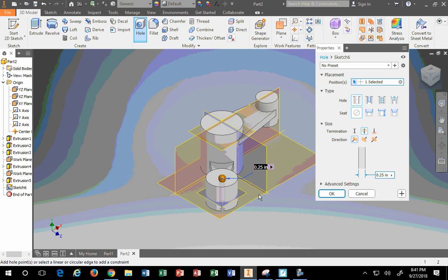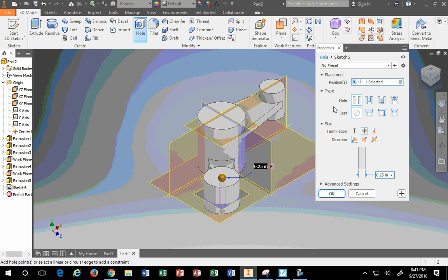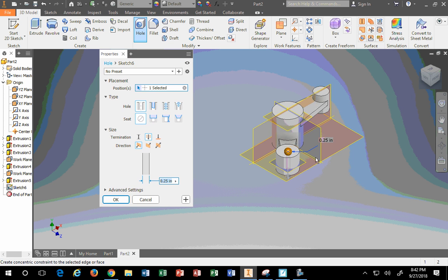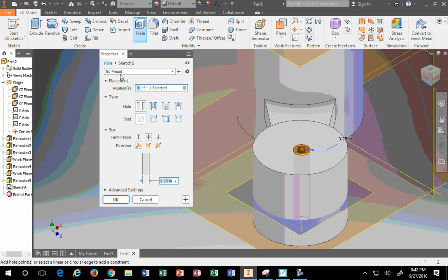When I drop it right there, base or location, sketch point, work point, what does it say? Okay, let's read that one more time. Let me drag it over to this side. Placement. Click a face and location, sketch point or work point to place hole centers.